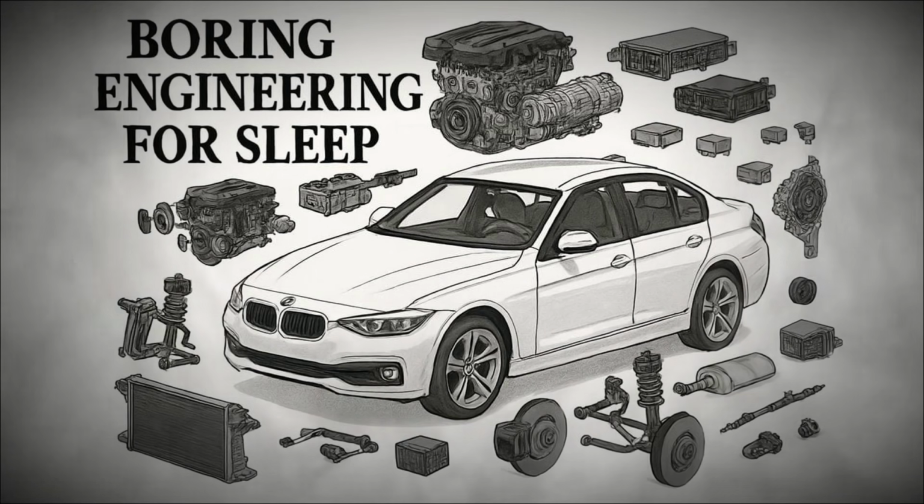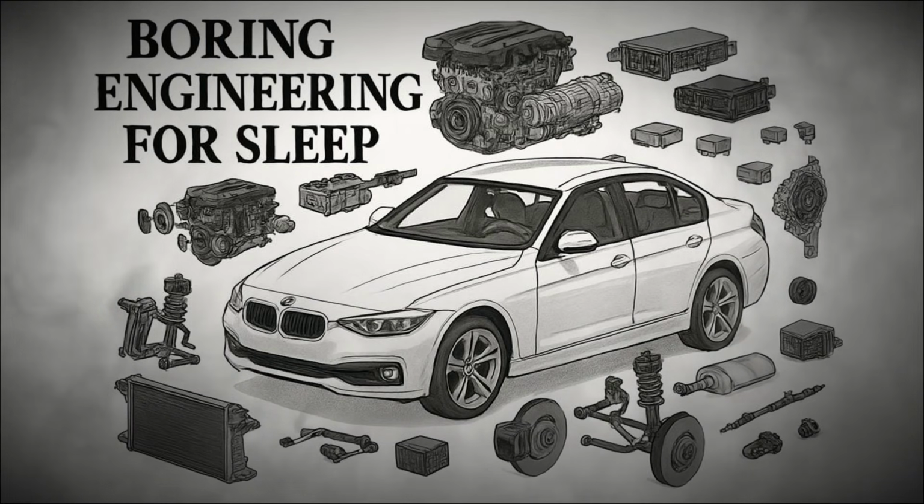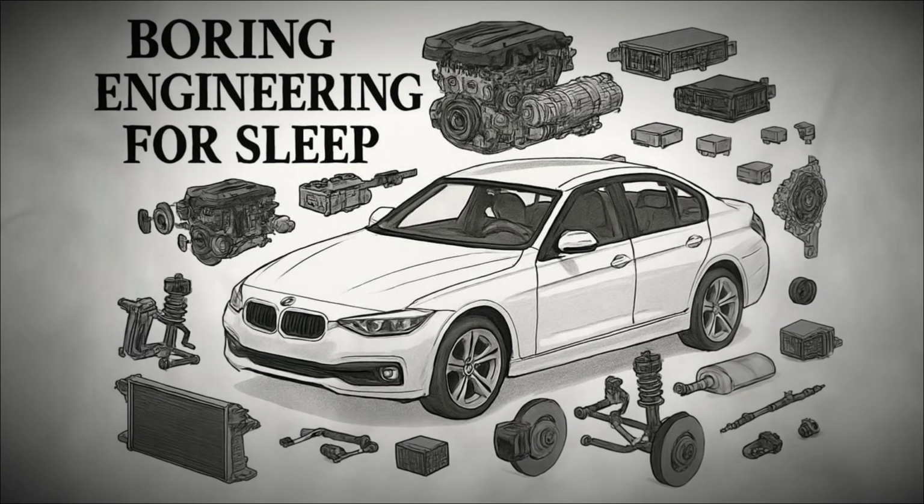Modern seatbelts also incorporate retractors with locking mechanisms that allow the belt to extend and retract freely during normal movement, but lock in place instantly during sudden deceleration. Pretensioners are often added, which use small explosive charges or electric motors to tighten the belt in the first milliseconds of a crash, removing slack and securing the occupant firmly against the seat. Load limiters are also used to release a small amount of belt webbing under extreme force, preventing chest injuries by reducing peak loads.